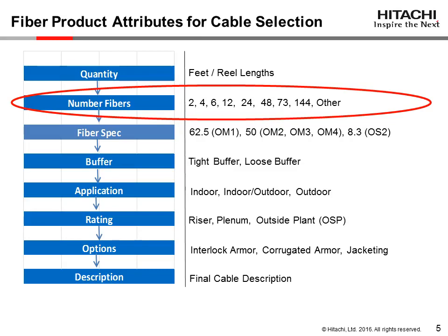Fiber optic cables come in multiples of 2 fiber increments and are commonly available in 6, 12, 24, 48, 72, and 144 fiber configurations. Nearly all network design engineers allow for a number of spare fibers to accommodate possible fiber breakage and future upgrades to the system, and typically increase the needed fiber count to the next available standard package.